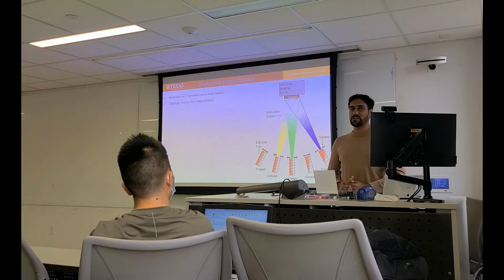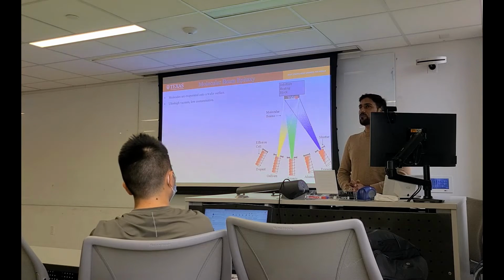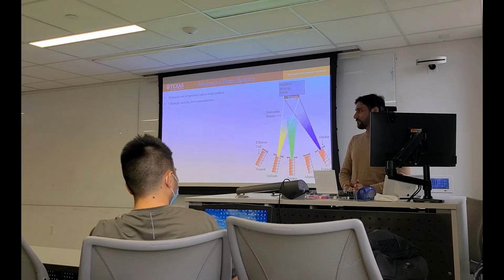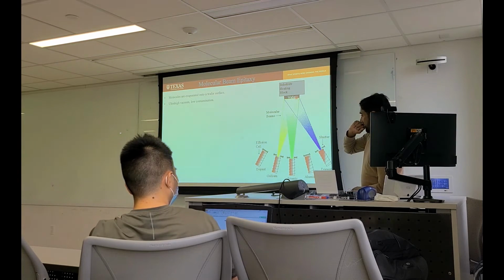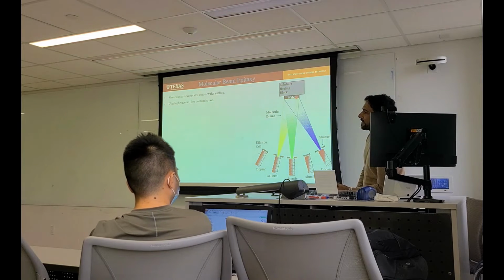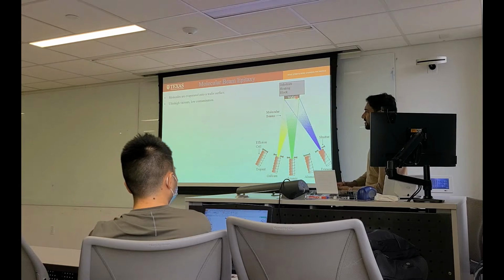When I talk about group 3 precursor for gallium nitride, group 3 precursor is gallium. Gallium is from group 3 in the periodic table, and group 5 precursor is nitrogen, ammonia, whatever we use here. The issue is that, for gallium oxide growth, you need a gallium source and an oxygen source. When the vacuum is very high, oxygen partial pressure is very low inside the reactor. In that case, you create oxygen vacancies, and the growth rate is very low.